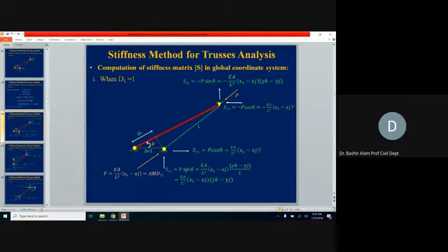Now, second, at the near end, if you see, S11 and S21 values are positive. So at the near end, these coefficients will be positive, and at the far end, they will be negative. So you can see here, negative and negative. So now we have generated the member force matrix elements, and the stiffness coefficient elements also.